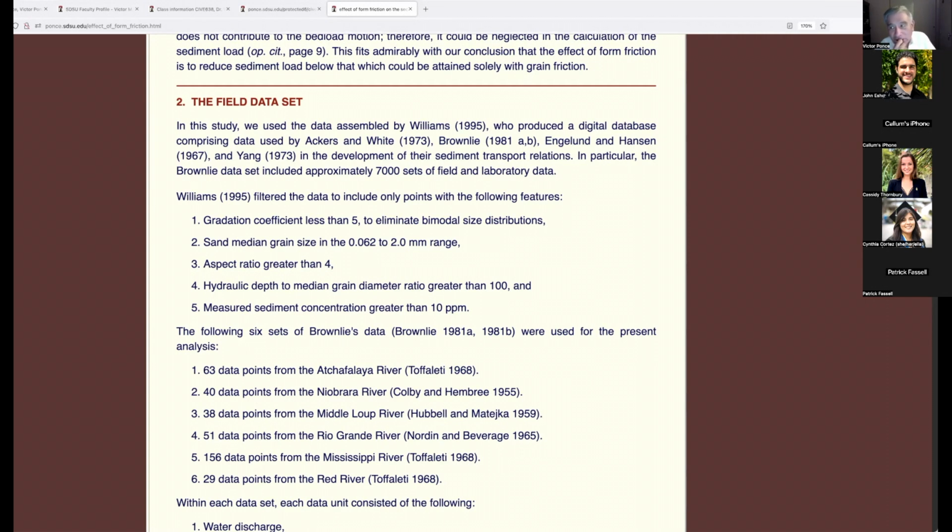If you go out there and look for a narrow channel in nature, it almost does not exist. I've seen 1 or 2 in my entire practice. I saw one in Colorado, with only 2 or 2.5 width to depth, but that was because of some other issues. When nature has its own way, the aspect ratio is usually 8, 10, 15, 20, even greater than that. Width to depth, which we call the aspect ratio.